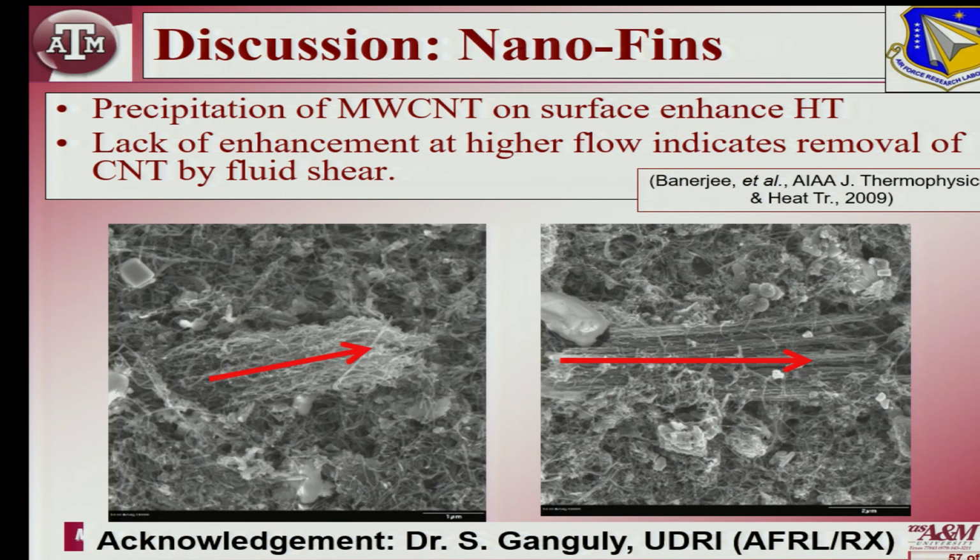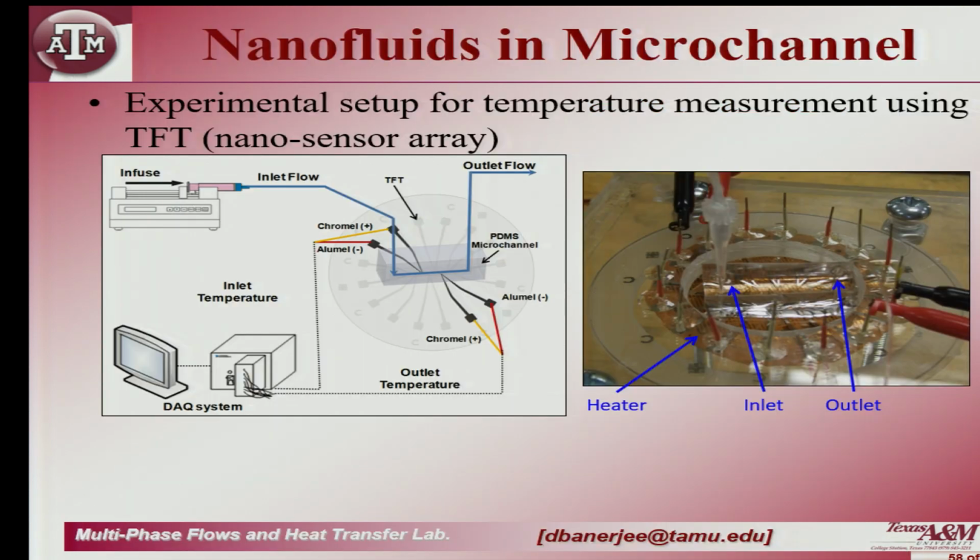Okay. So, to answer that question, we got funding from Qatar Foundation in Doha, which is their national science foundation, or you can say that is their Department of Science and Technology sort of. So, we made a micro channel, and we put these nano thermocouples in the micro channel to measure the temperature along the micro channel. Okay. And then we did the experiment with water, we heated it from below, and then we repeated the experiment by putting nanoparticles in the water, silica and titania, which dissolve right away into water, give you a very stable colloidal solution,